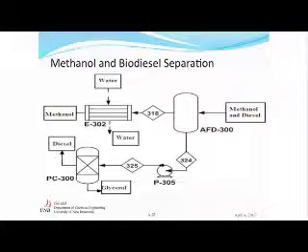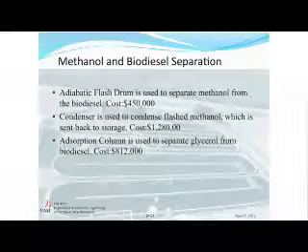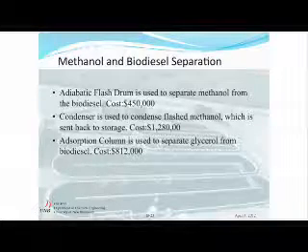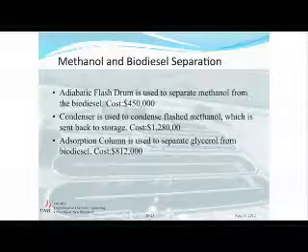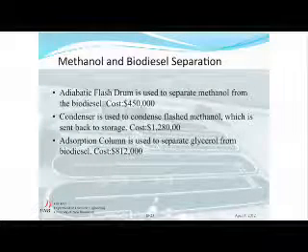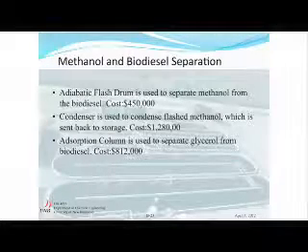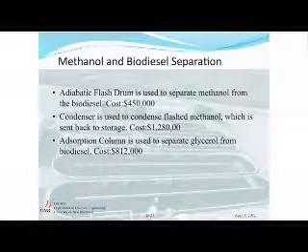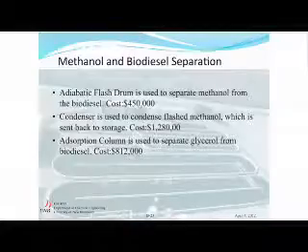Now we're using adiabatic flash drums to vaporize the methanol out of the biodiesel and glycerol mixture, and we are condensing the methanol and sending it back into storage for reuse. And the glycerol, the co-product, is separated using adsorption columns, and so we're producing the biodiesel from this.